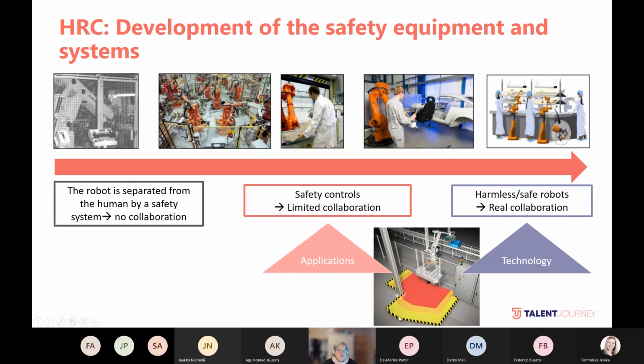As long as the human remains in the green area, in other words, furthest from the robot, it can operate at full speed and power. If a human then steps into the yellow or orange area, closer to the robot, it slows down its activities to the level of collaborative activity.